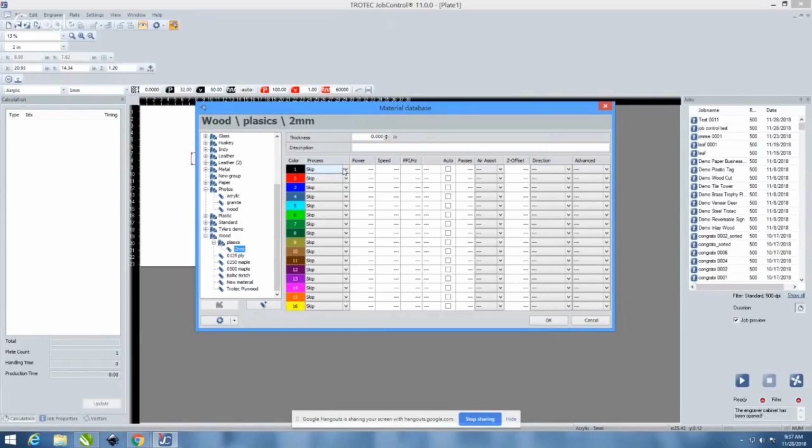It doesn't just have to be the matrix. You can literally engrave a half-inch square to test, and then keep engraving it at different power settings if you want. The grayscale matrix just makes it a lot easier because it gives you a bunch of little squares all together in different settings. Yeah, so if you just want to adjust it a little bit, just do one square at a time.